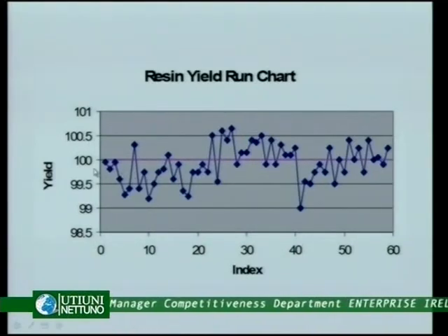In other examples, we can see different types of run chart being used to capture different types of information. In this particular chart, we are looking at the yield for the creation of resin. And we will see fluctuations around the target line. It may become possible for us to look at and examine why we seem to be getting better than 100% yield. The possibility could be here that at this particular time, certain characteristics of the process were being run better than we understood was possible. So by looking at what is being done at these times, we may learn more about our processes.